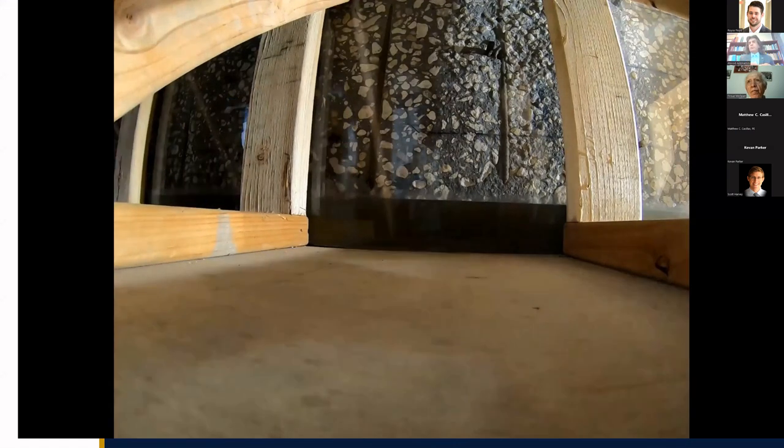And so this ultra performance concrete doesn't have aggregate, and it flows into very small spaces, 1/2 inch, 1 inch, and you can wrap your deficient bridge elements with the UHPC, and you can get a product that's much better than the original concept.